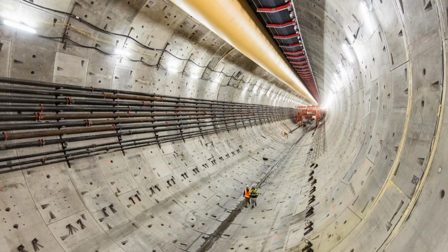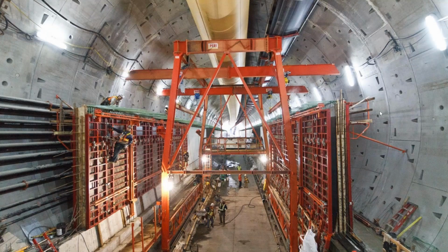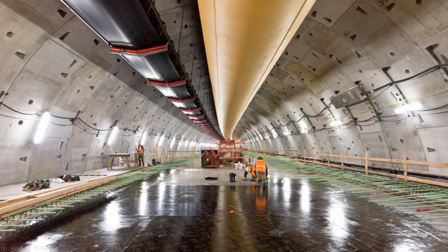Some pictures inside the tunnel. And here's bring in the concrete truck, and they pour cast-in-place concrete to pour the lower foundations for the walls to come up. There's the vertical wall forms, and all of these things travel through the tunnel. They roll on rails with the traveling forms. And the upper deck, this is cast-in-place concrete.